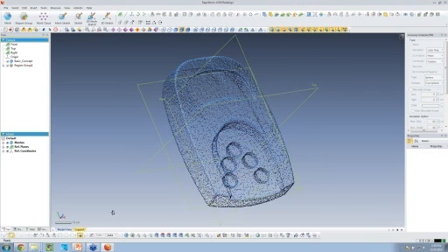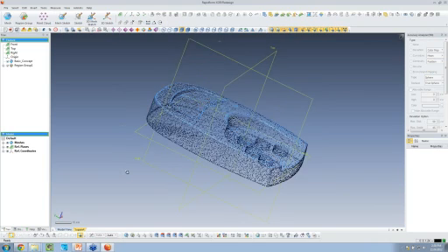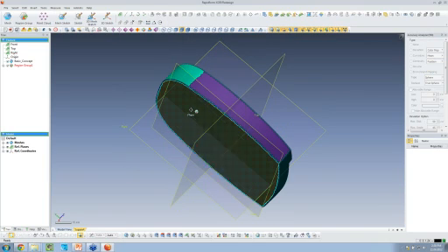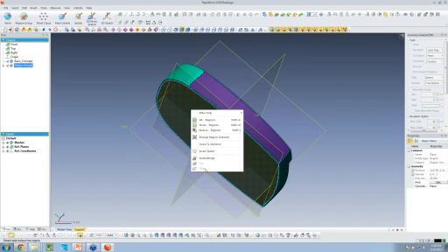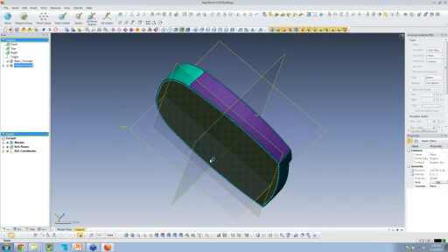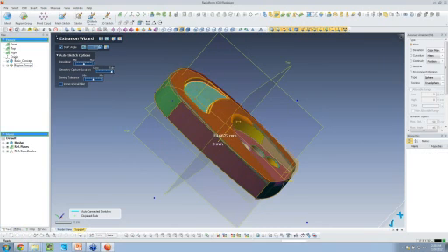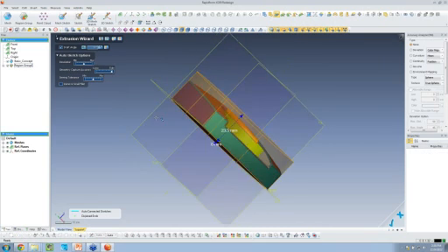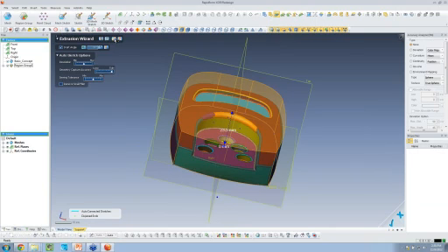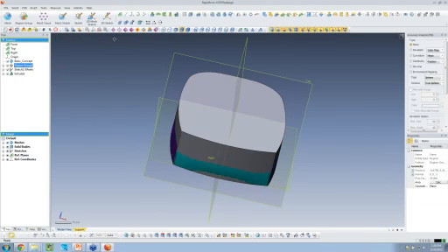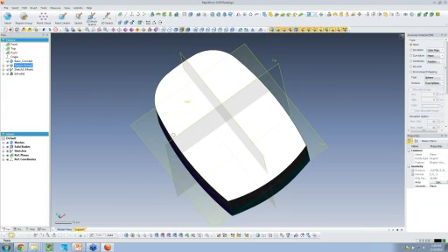So earlier I selected that plane, and that's the surface, and I did these extrusions. But now we've added some new tools where we employ some wizards and some automatic features. These automatic features are available by right-clicking, and I can say Insert Merge. And once we do the Insert Merge, we automatically get that extrusion that quick. So automatically this extrusion wizard was prompted, and we can automatically extract that. See, what was it, about 3, 4, maybe 5 button clicks? I have this 3D solid.